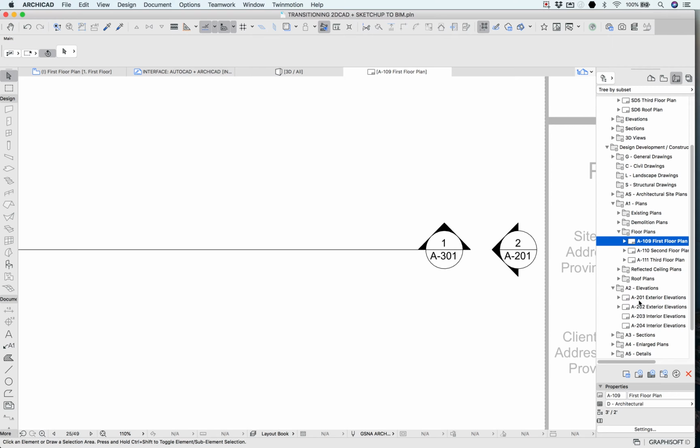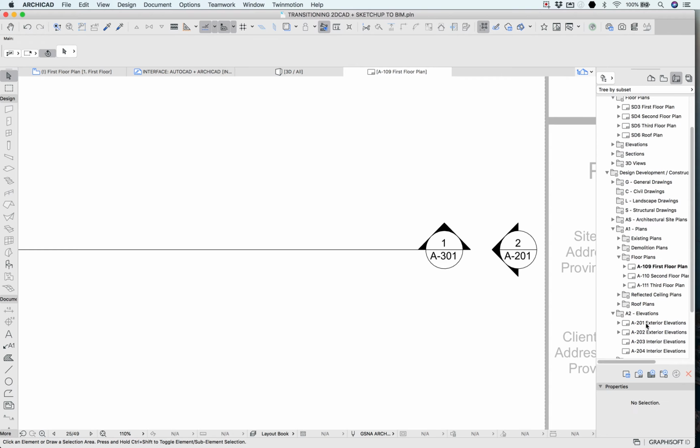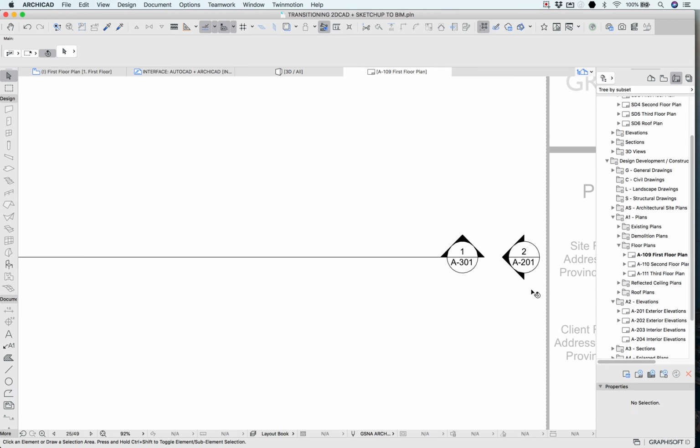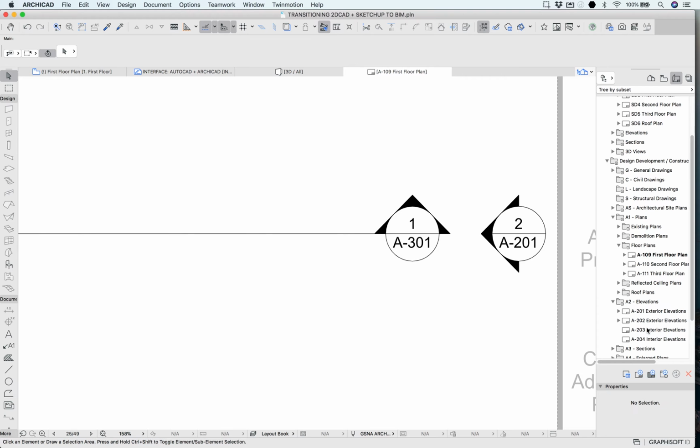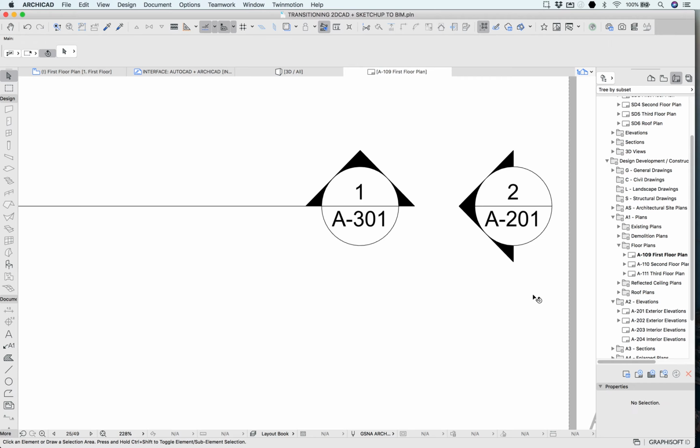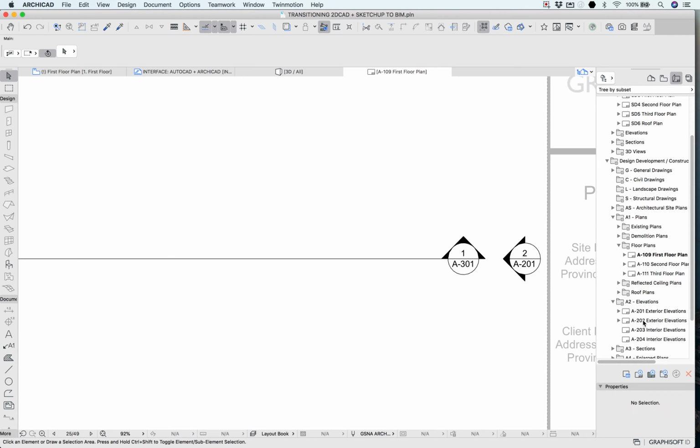So if my elevation drawing, just to give you a preview into where we're headed, if that drawing switches or I switch my page number, it's going to renumber itself here, but it's also going to renumber itself within our set, right? So you always have this changing information that will be updating as you move it throughout your drawing.